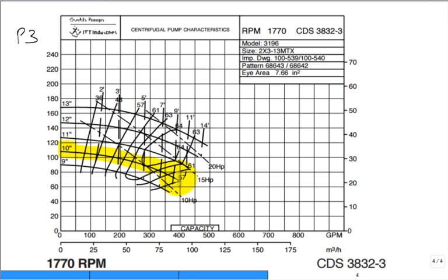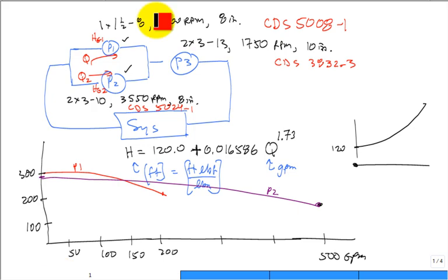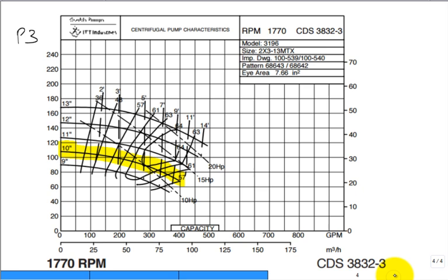All right, well, first of all, can you see from the diagram that the sum of the two Qs right here has to go through pump 3? So do you think the sum will be up in the 500 GPM range when pump 3 really doesn't want to take 500 GPM? Do you see that?